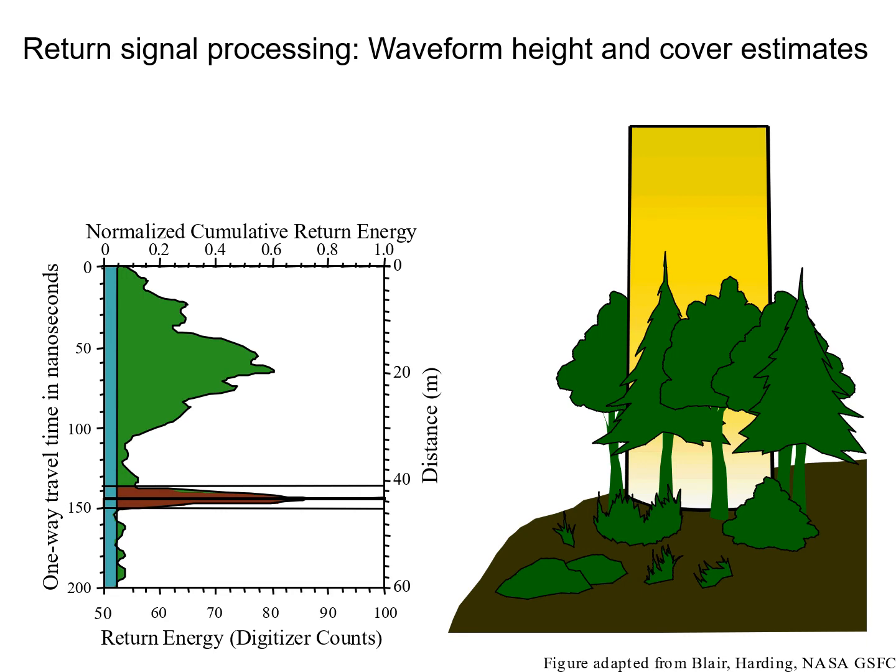You might see a nice little gap there, like at 110 through 130 nanoseconds, where you have a lower amount of foliage in the understory. And then in this case, we see a little bit, maybe a meter or two of increase, and that could be understory vegetation. You then hopefully get some kind of ground return. So some fraction of the energy gets through the entire canopy and is returned by the ground.